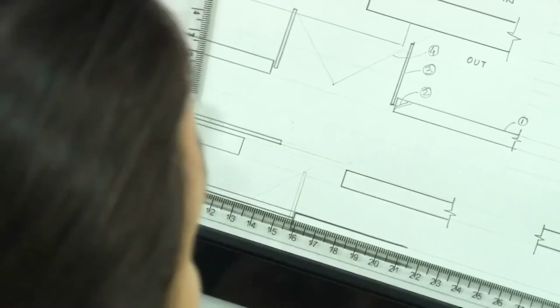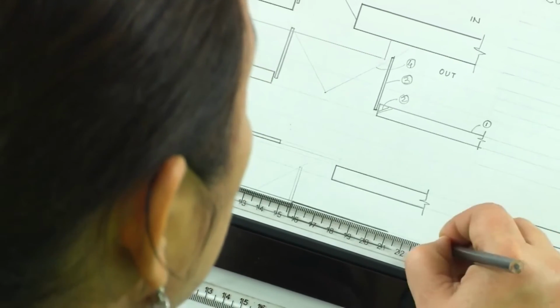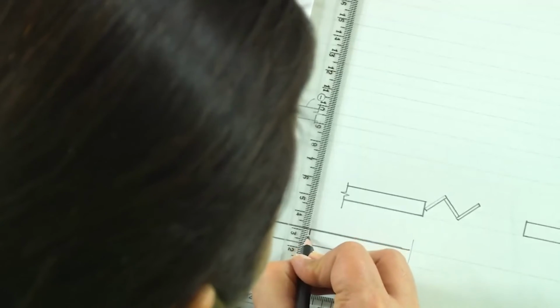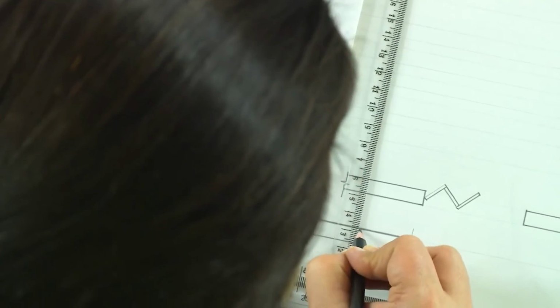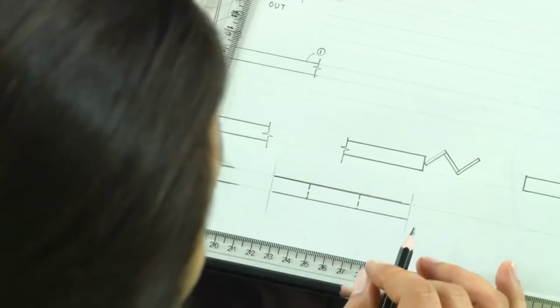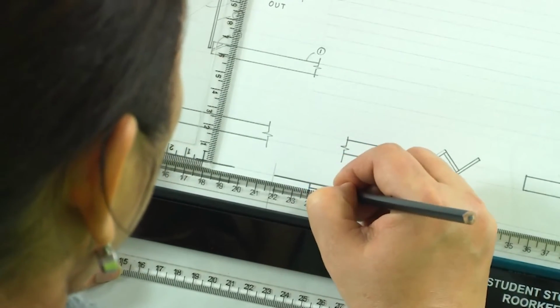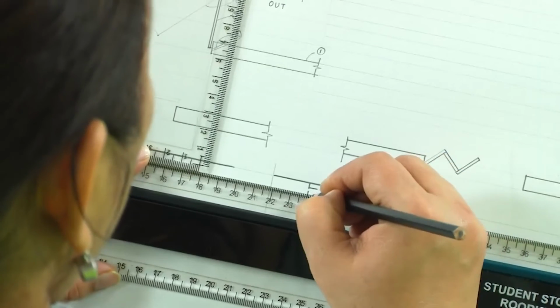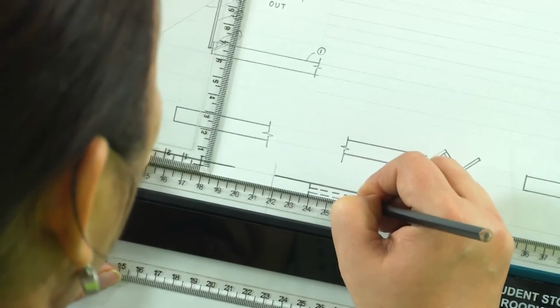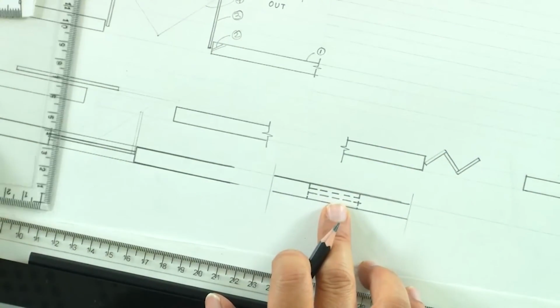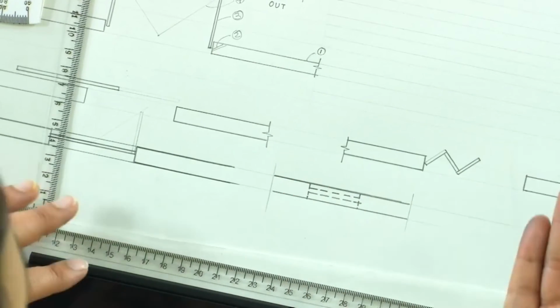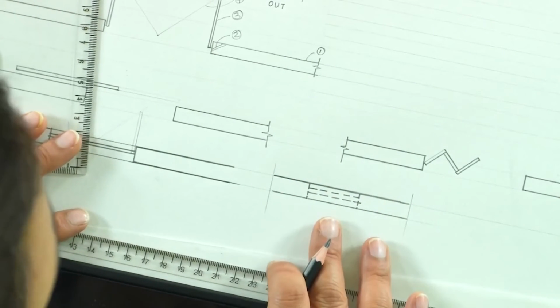In case it is a ventilator, suppose we have a ventilator. Now, the ventilator is not being cut at a 1 meter level. So, what we do normally? We will draw the dotted line because it is not seen directly. So, if we have a dotted line being seen, we will assume that there is a ventilator at a level higher than where the section is being drawn from.